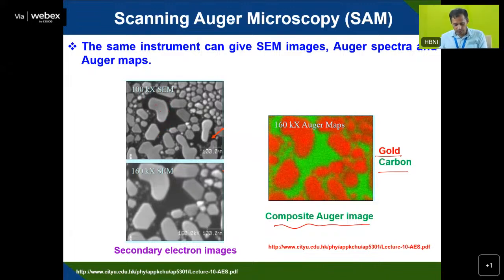Auger electron spectroscopy. So both XPS and Auger electron spectroscopy are very useful for surface characterization. They give information about oxidation state, chemical bonding, and local structure, and quantitative analysis is possible, as well as imaging, since you can combine them with imaging techniques. You can see mapping by X-ray mapping or Auger electron mapping, and do all these elemental identifications. And then you can also see the depth profiling by either a destructive or non-destructive way.